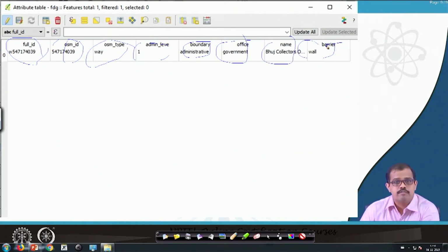These are the attribute information that is there. Now for example, it also has X and Y location. Maybe I have not completed the entire attribute table. If I have completed the entire attribute table, with the X and Y location you can even calculate the area of this particular attribute, just by using different operations here. So this is how the attribute table can be accessed.